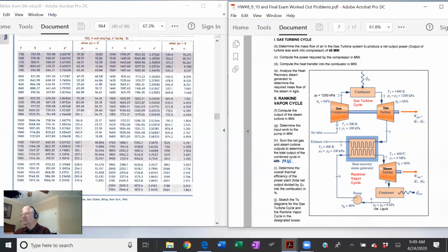This is a combined cycle. Very, very important. This is what is used. Almost all natural gas plants run on a combined cycle. And it just makes sense. All this hot air coming out of this turbine, let's use it as practically free. Now there's a big capital investment required for the heat recovery steam generator. I'm sure it costs millions of dollars, but as far as operating expenses, once you get it done, it's probably just a little maintenance.